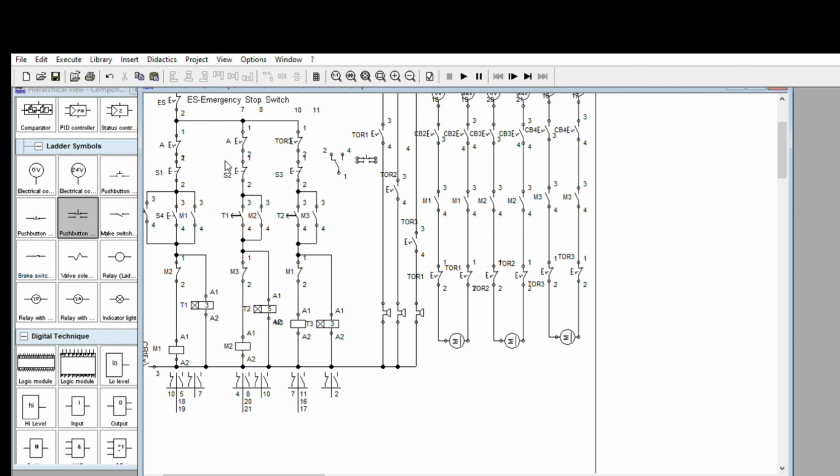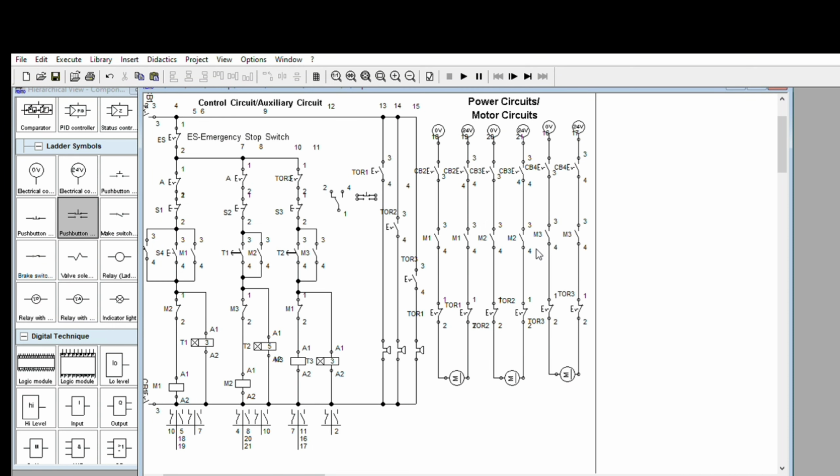At that instant when this one is turned on and this one is turned on, and you only have one interlock, in reality you will have a symmetrical short circuit. It will occur between the transition of the two contactors. Because this will open first when this is already turned on. See, in the two-step operation, we'll change this one to 1 second. So you can see that.